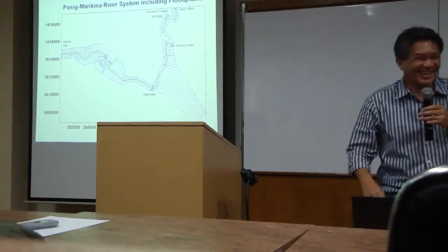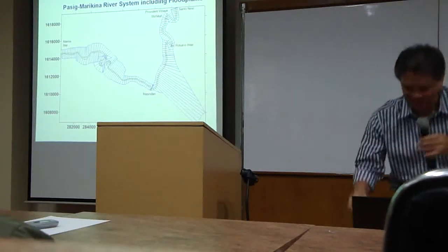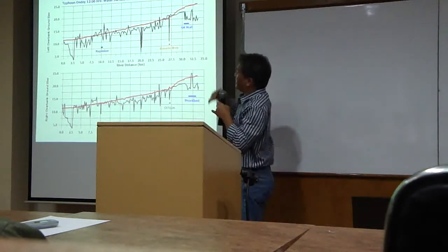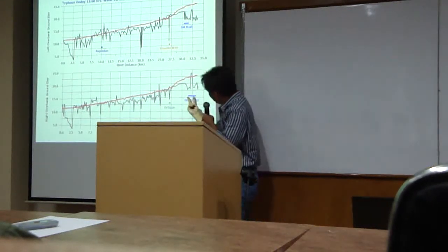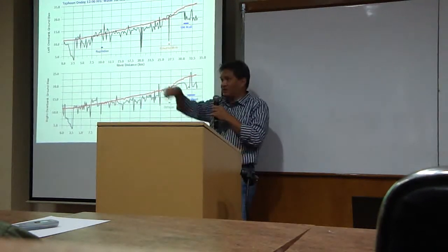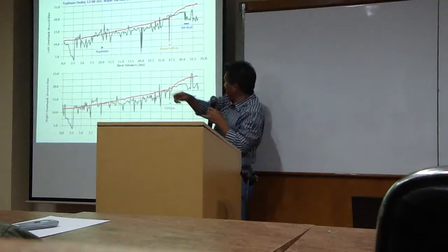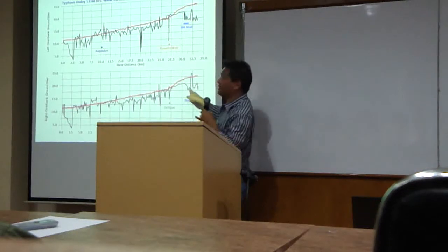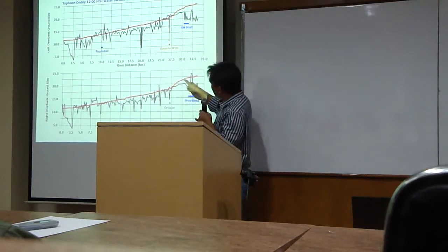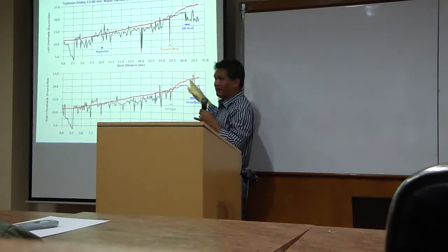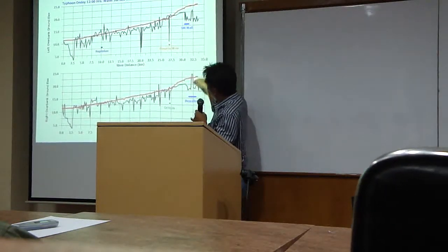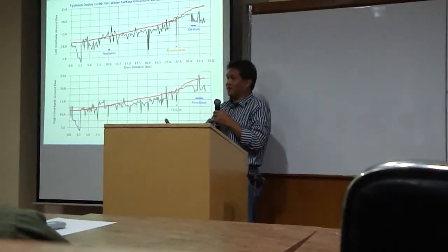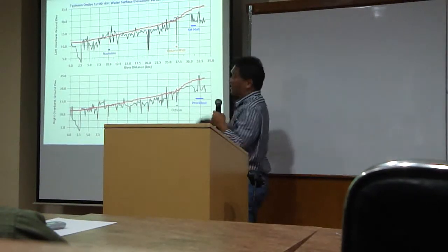Marikina, the famous now SM Mall, as we'll discuss later. So what you'll see, if you are looking downstream on the right-hand side, around this area is the Provident Village. This is a loop actually, right? It was a river bend that goes like this. So the river banks there is about, if you look, 17 meters. The river went all the way to 20 something. Now, if you had a wall, actually this was considered to have a wall, but this part no wall, then everything just gets inside the village, right? And what happened? I think there was a break.